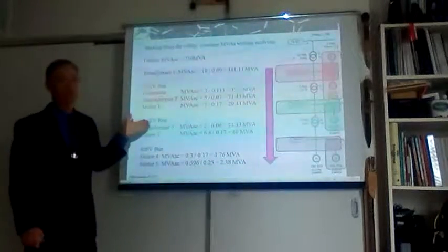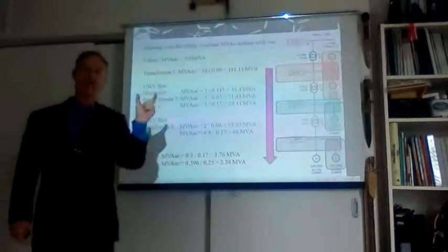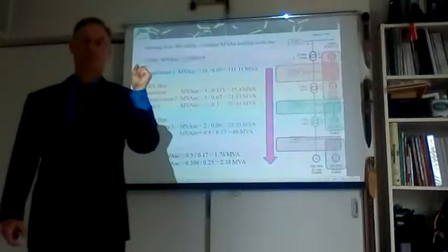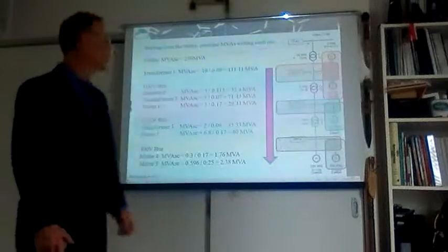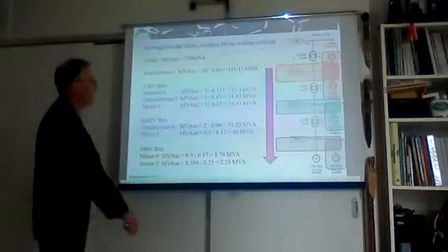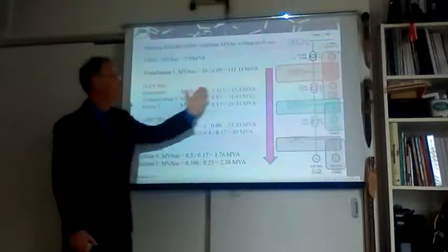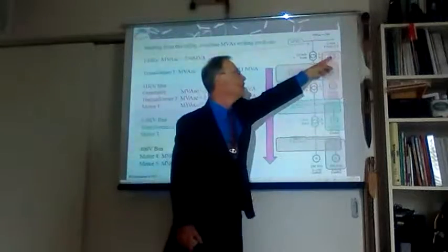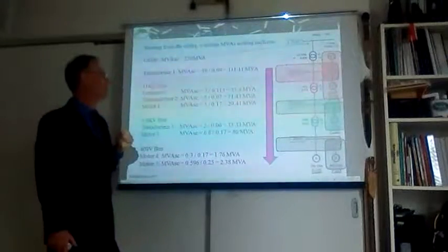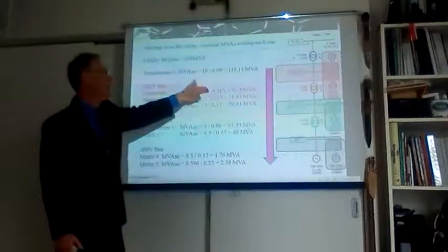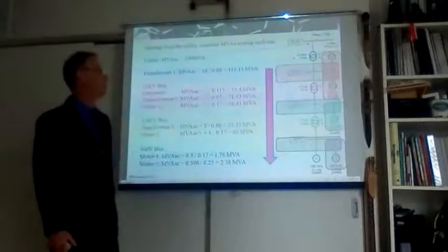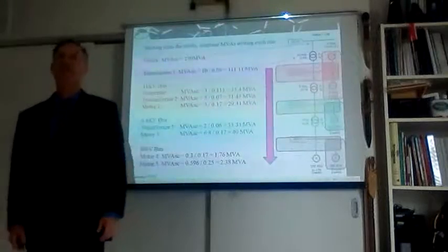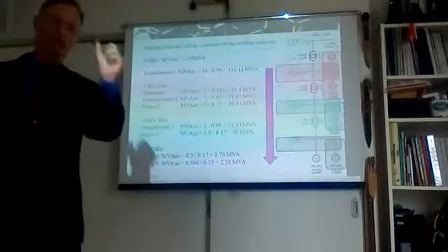All those calculations are in effect for the first 2-3 cycles during a short circuit. And that's the way we continue for each and every component. Like for the standby generator, we take its 3 MVA and divide it by 11.3%, which will give us 33 MVA during a short circuit.